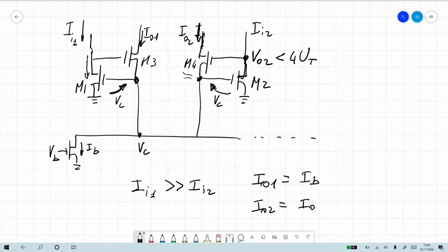My question there was more like, if we see this winner-take-all circuit, do we always expect one of the branches to be working properly in saturation, and the rest of the branches to not be working well into saturation? That's going to be the case when you have sufficiently large differences in the currents. Now, this sufficiently large is exactly the third point that I said we would analyze when we have small signals.